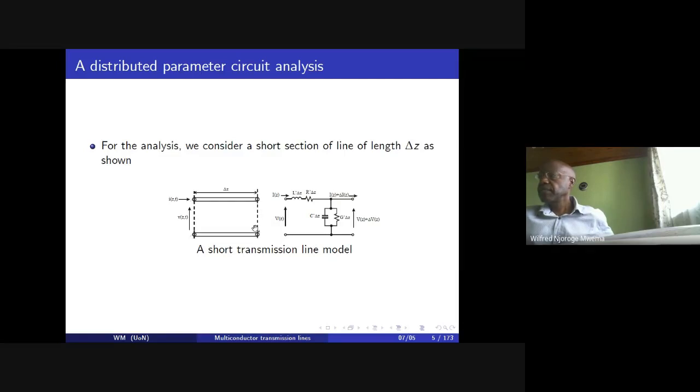The lines you see put at the ends of the sections are important and are usually called the reference planes for all measurements we'll be dealing with. Therefore, whenever you use transmission lines, or when you draw a transmission line section, I expect to see you putting these dashed lines at the reference planes.